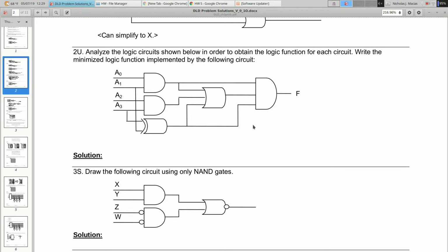Once I've got intermediate values right here and here and here, right? Now to find the output of this is just an OR of 3 things. I look at F1, F2, and F3, and if any of them are 1, this point F4 becomes a 1. So now I've got columns for F4, F1, and F2, and anytime all 3 of those are 1, my final value F is a 1.